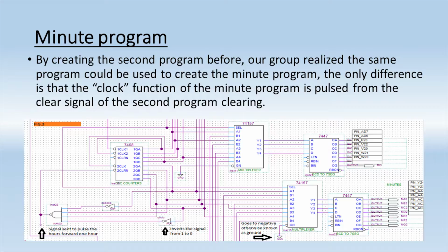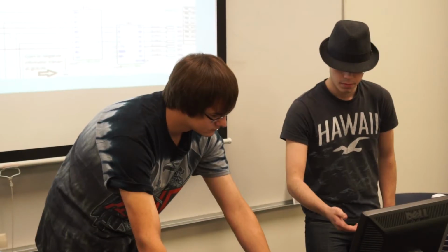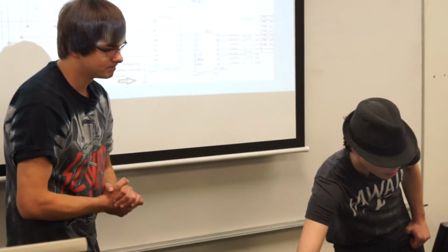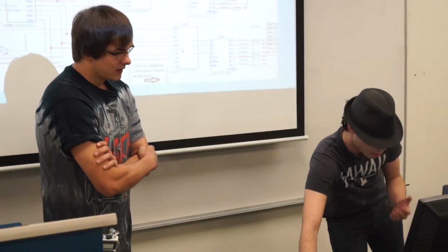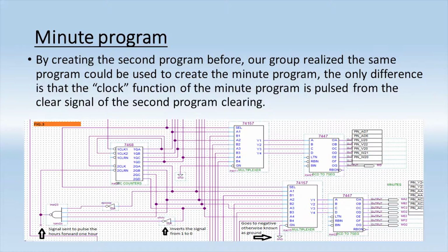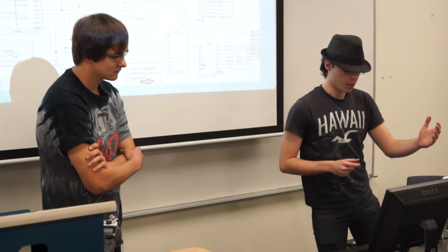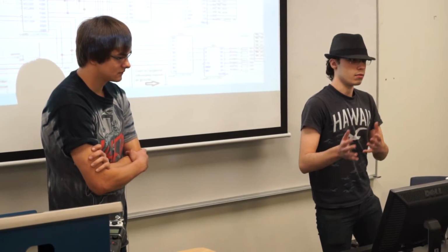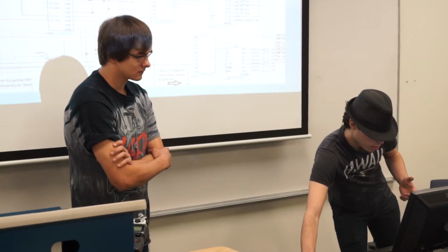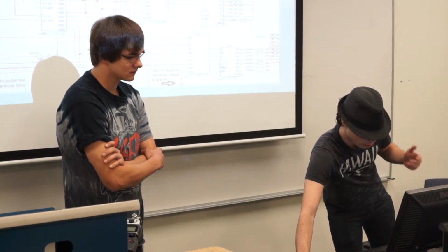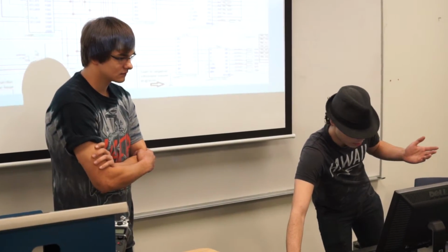Well, basically, the numbers coming up from, if you can see the mouse, this inverts the signal coming from reading our multiplexer, just reading the numbers going into it. We wanted the clock to roll over at 60, as I was mentioning, and our NAND gate was reading when a 6 was present through binary, and was sending that clear signal to clear our minutes.